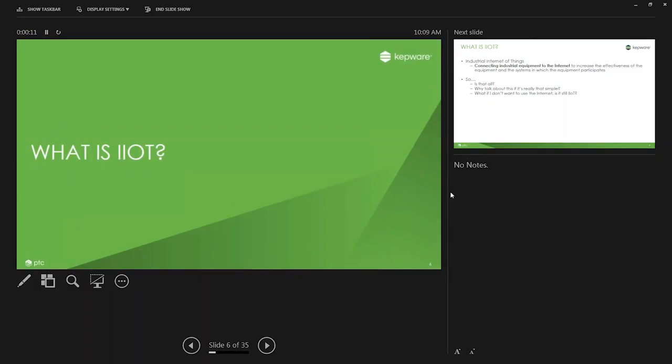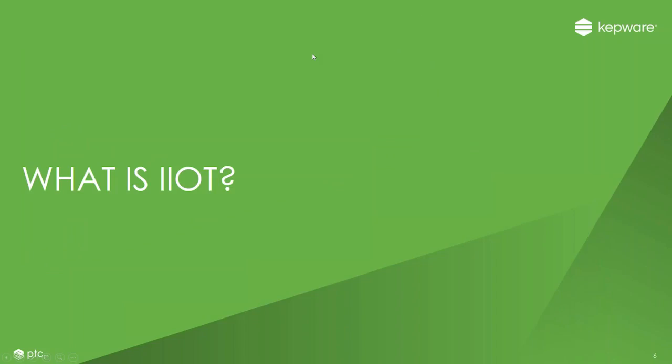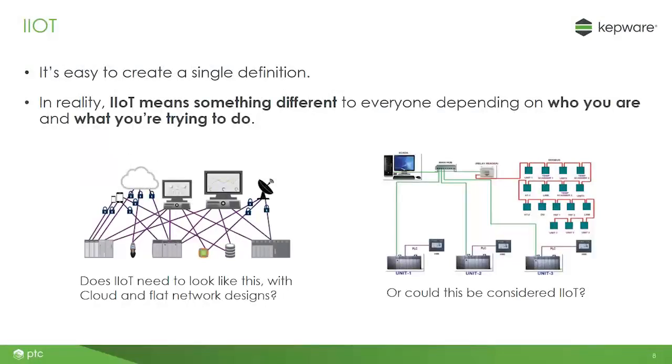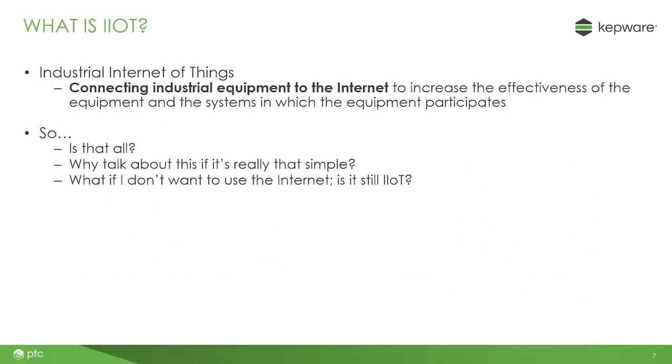The other question was about Azure cloud analytics that we support. So with our IoT Gateway, we really use some standardized mechanisms to move that data, and ultimately it's what those analytics tools can ingest for data specifically. So RESTful interfaces and MQTT are commonly used in this space for accessing that data. So whether it's Azure, whether it's AWS, or I should say, other industry or solution providers' platforms, typically we can use our tools to be able to move that data into those platforms.